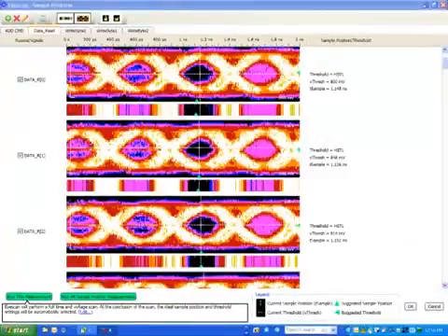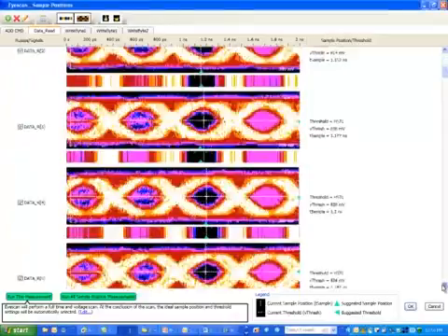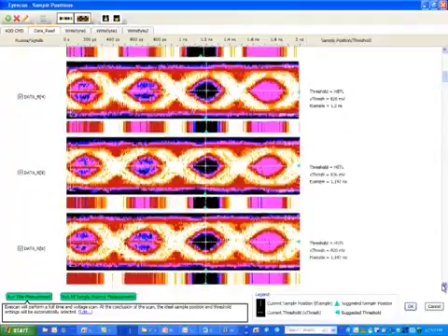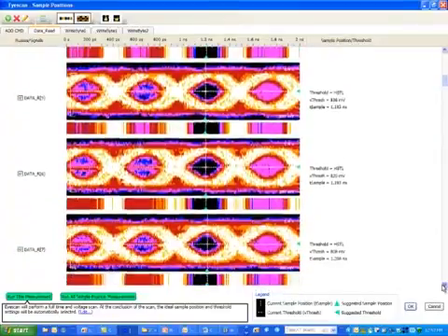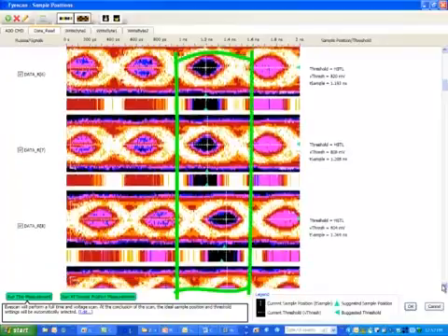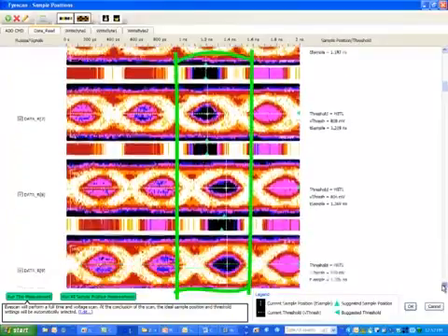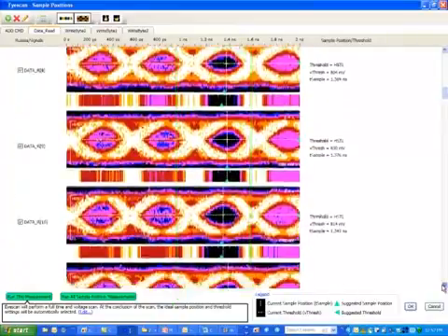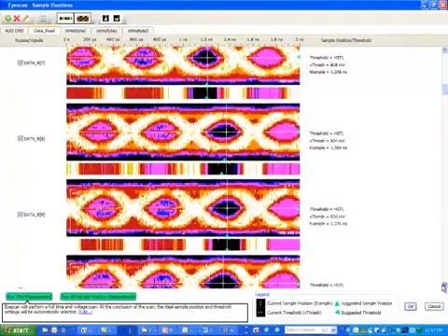We are viewing the read eyes. Scrolling through the data, we can observe the signals relative to each other for quick signal integrity insight. We get all of the signals in the system. Here between bit 7 and 8 we see a byte lane shift, which is expected. Note that almost all of the eyes are relatively the same size. That is, at least for the first 2 byte lanes.